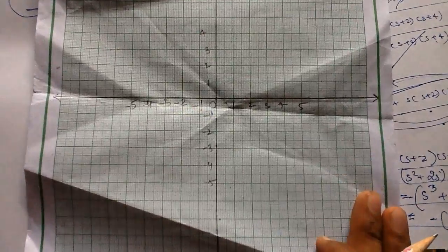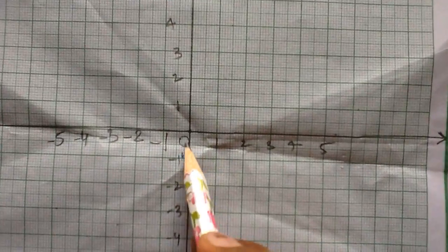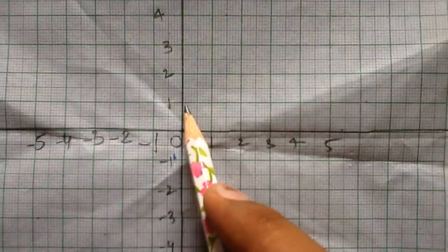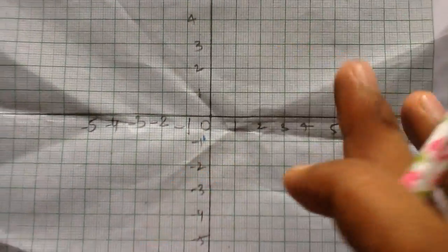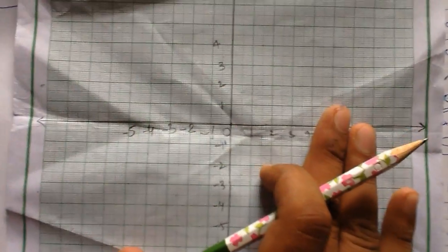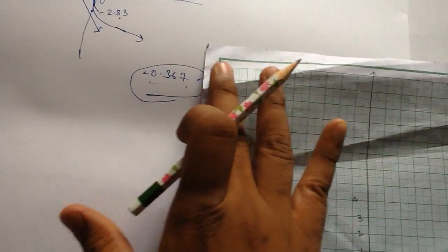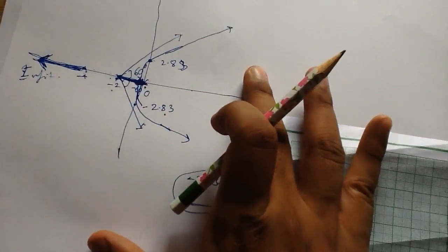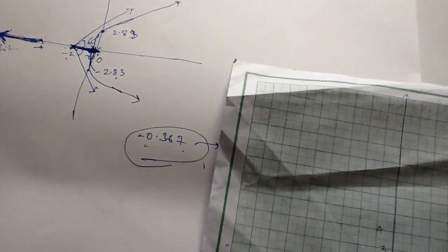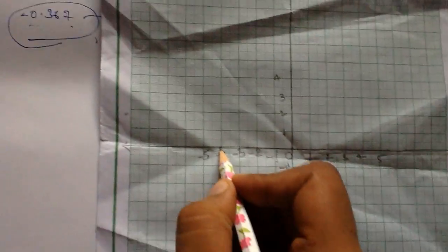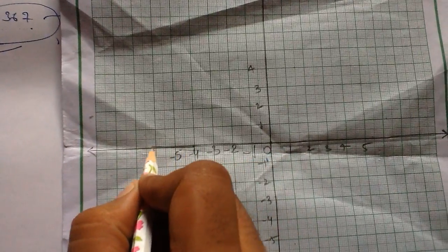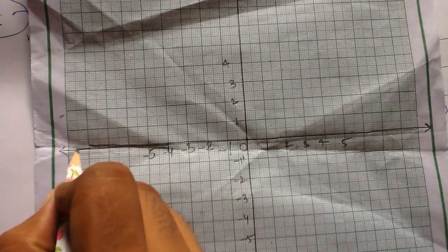So this is my graph sheet. I have marked the readings to a scale of 1 centimeter equal to 1 unit on this graph sheet on both the real and imaginary axis. So always while drawing the root locus, even on the graph sheet, these values of your rough work are not just enough. Also keep beside you your model graph sheet. As you already have, from minus 4 there is a branch going to infinity. So just darken that branch.